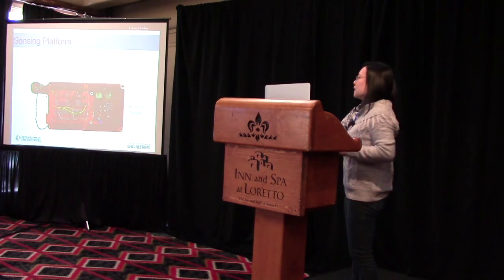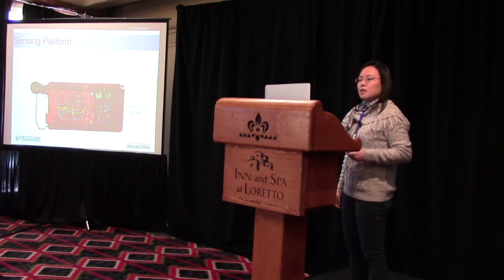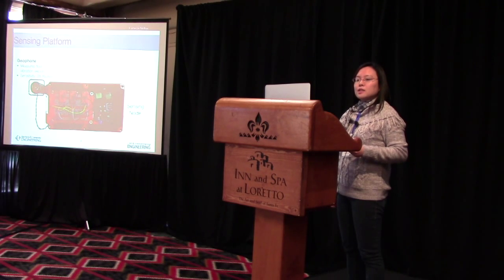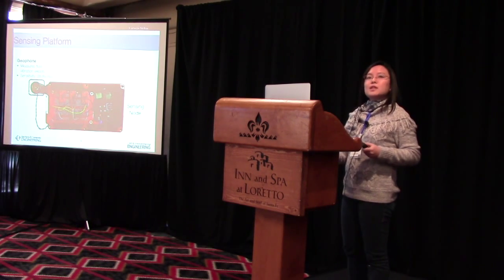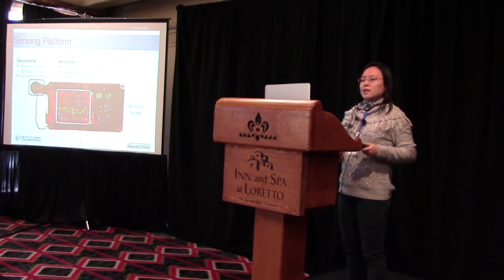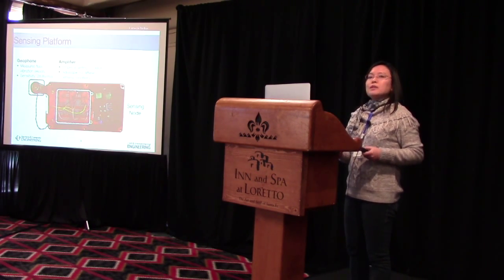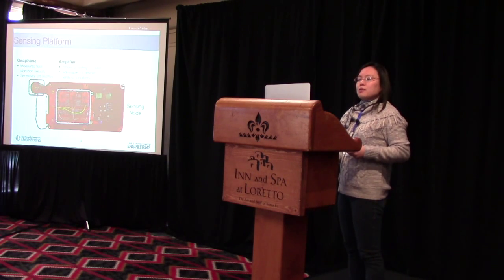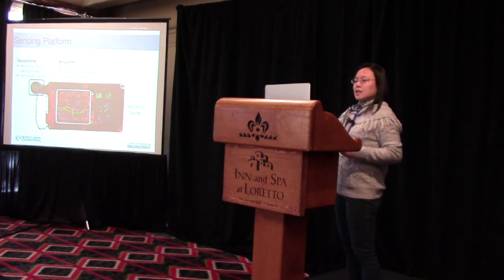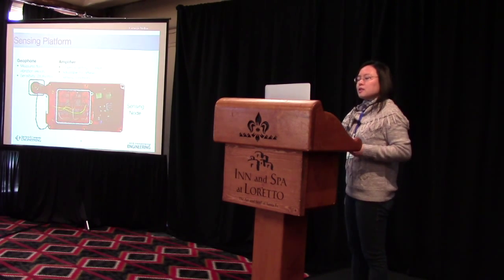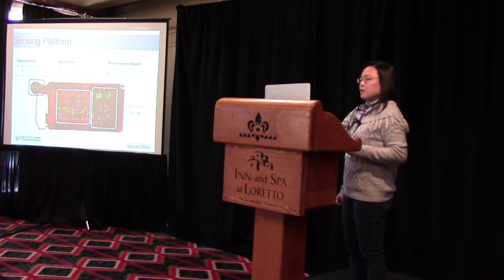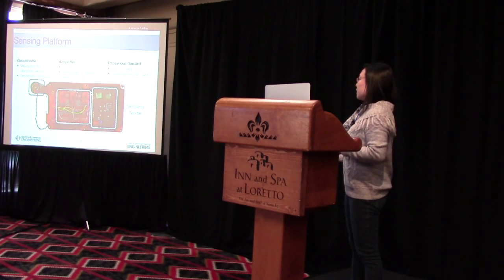This is an example of our sensing node. The geophone is used to measure the floor vibration velocity. The vibration induced by footsteps is of very small amplitude. So in order to conduct further analysis, we amplify the signal in our experiment with an empirical setting of 1,000 times. The amplification setting is adjustable for different sensing conditions. Then the processing board digitizes the signal and stores the data.